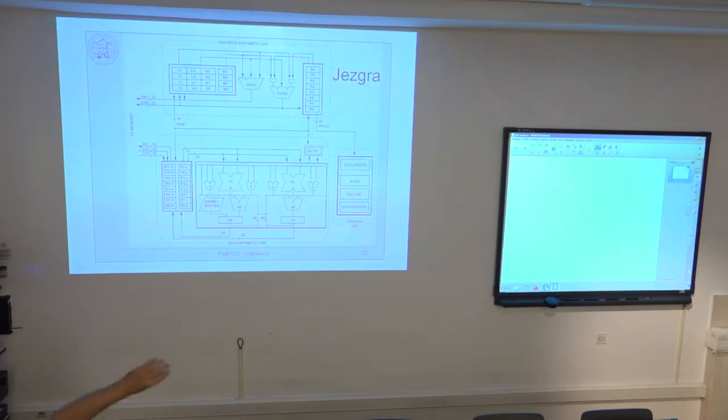Okay, now that I have 2 effective addresses, what I do is fetching from memory from these 2 addresses. Of course, if I have only one bus to the memory, one address bus, one data bus, and I want to do 2 fetches, it must be done in 2 cycles. But nevertheless, to solve this, you might have cache memory that is multi-ported, that has multiple blocks. One block for, let's say, first data space, another block of cache memory for another data space, and finally another block of cache memory for program space.